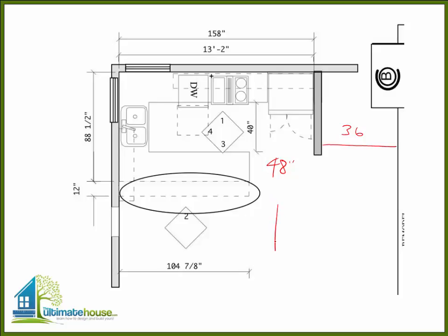and oftentimes when I have a plan, I create on CAD a box 3 feet by 3 feet, and I literally move this box around in and out of areas to sort of see how comfortable it is for traffic. And when you have a kitchen, a 3-foot corridor would be very narrow. 4 feet really worked out quite nice.